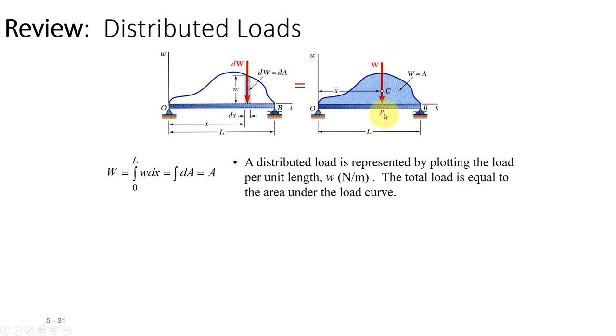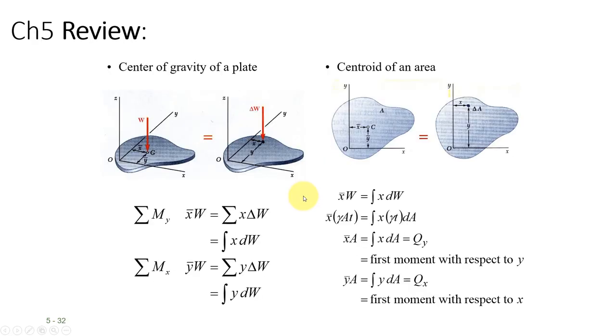And you have this x times weight, right? Inertia is going to be very similar, but instead of x times weight, it's going to be x squared. We're going to add a squared term to this center of mass idea. So if you go through your Chapter 5 and remember how we found centroids, finding the moment of inertia is very similar to finding centroids.